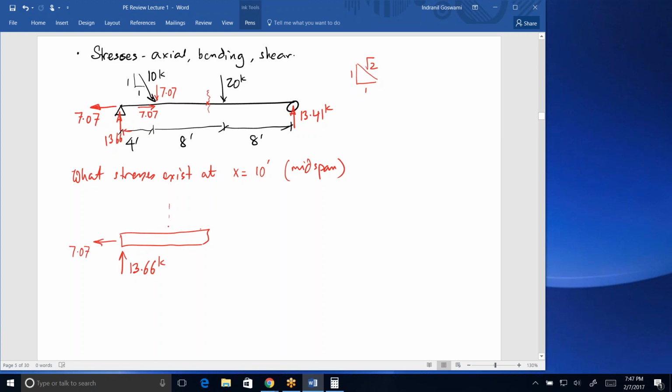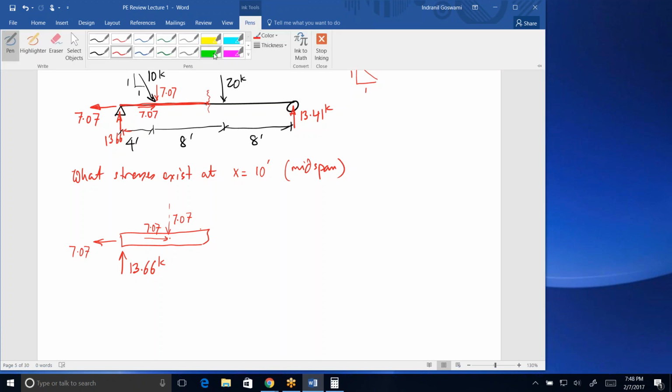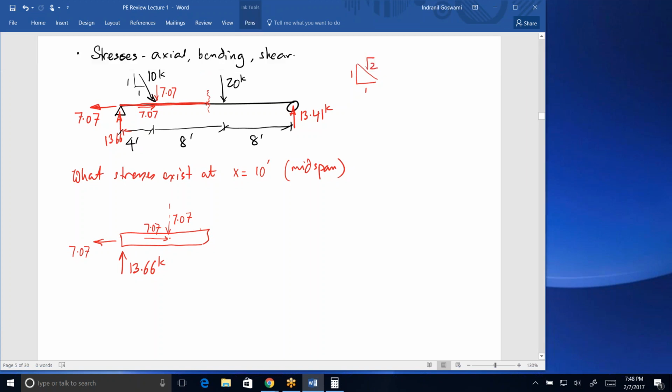and I can put in my components like that, right? So these are all my external forces and external reactions acting on that half of the beam, because I'm looking at the free body diagram of that portion to expose what's going on at midspan. So at midspan, you have a normal force, which is typically written like that. You have a shear force, which is typically written like that. How you represent your shear and moments at a particular cut depends on an adopted sign convention.